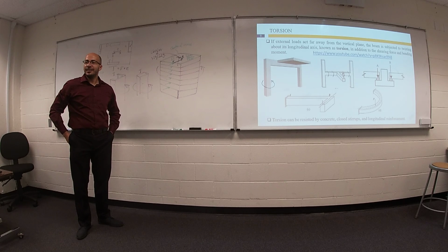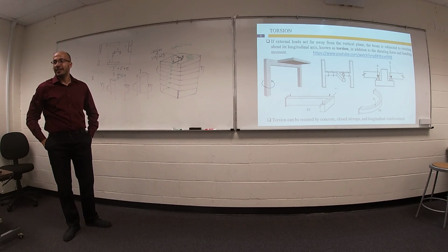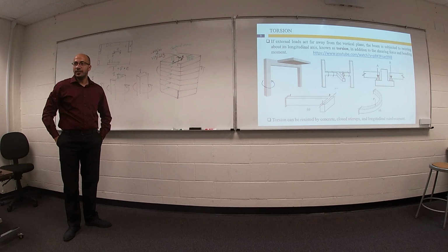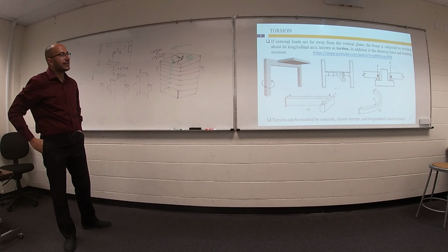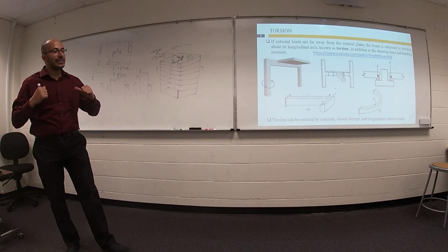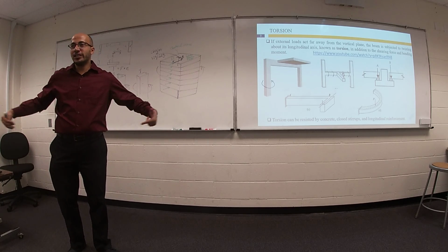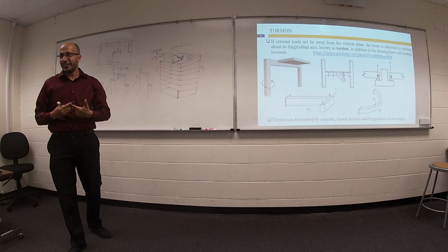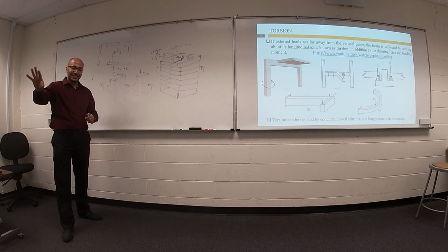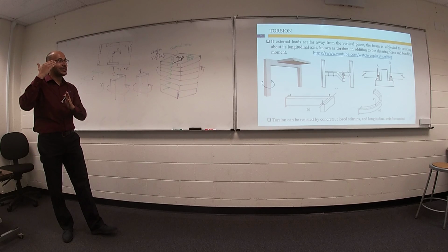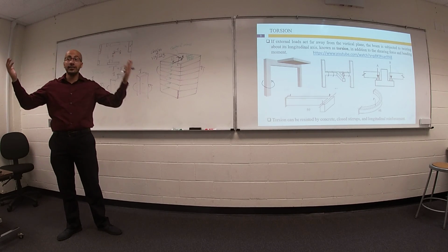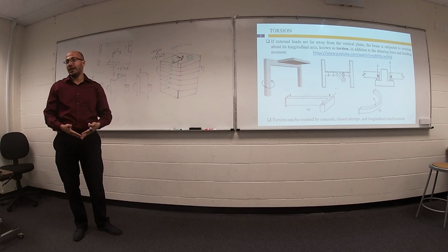If you put a strong column in the middle of the building, would that work? Yeah, sometimes that's fine. But the location of your column doesn't depend on my decision only, but on the architectural plan of your building. The first thing you need to do is respect the architecture. I have a hall or stairs or whatever, so I cannot put a column at the middle.